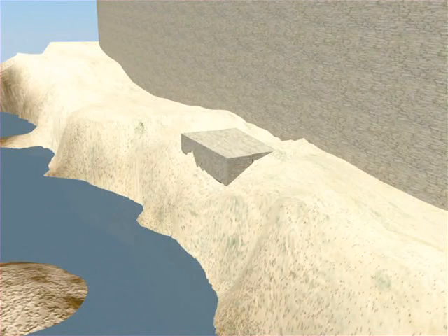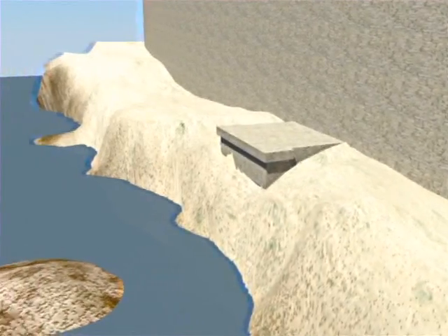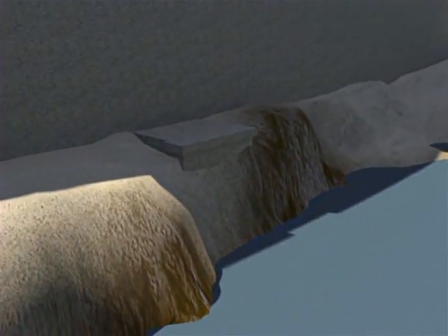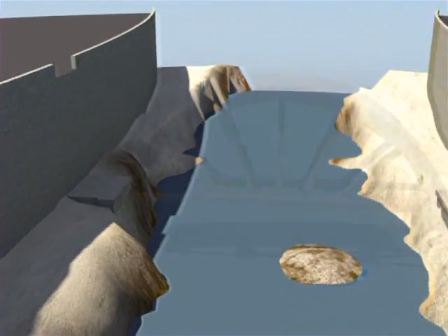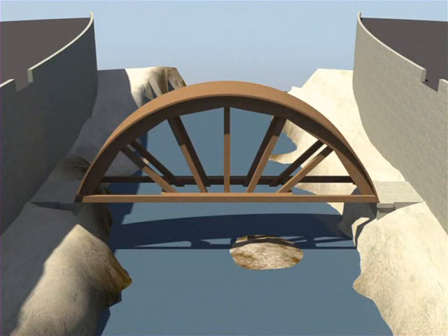Now we add these two stone projections just above the foundations on either side of the arch. These are ledges that were actually used to support the temporary wooden centering that was used to hold the arch up during construction. It's quite noteworthy that these ledges were actually engineered right into the structure of the bridge, clear evidence of a skill that even modern engineers often find challenging, accounting for constructability requirements while the project is actually still being designed.